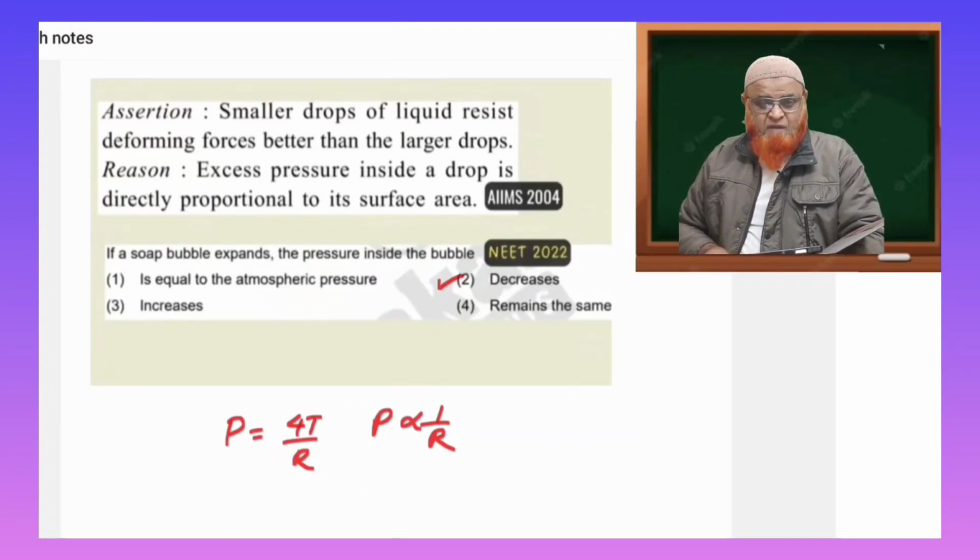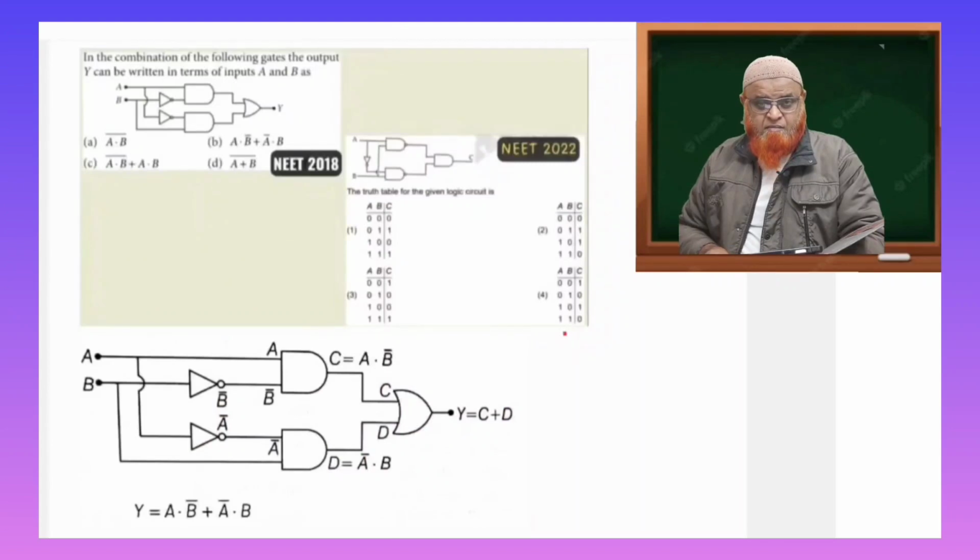Now, this type of question is repeatedly asked, many times, even double times. You can just see here. If you consider input as A, directly you'll write A. But if you observe B here, it is passing through the NOT gate, so you have to take the complement. And you know this is an AND gate, so A dot B bar is nothing but A dot B bar outside. And in the below, what are you going to see here?